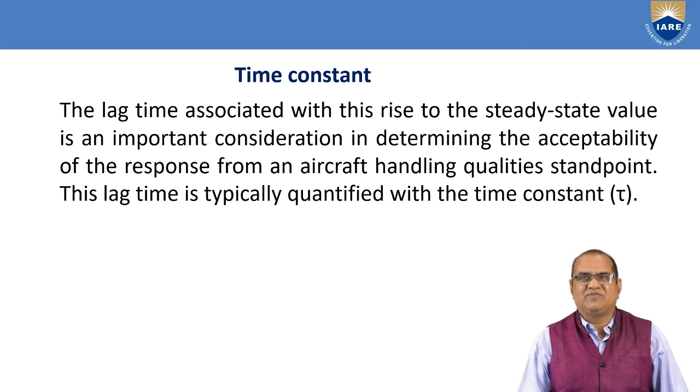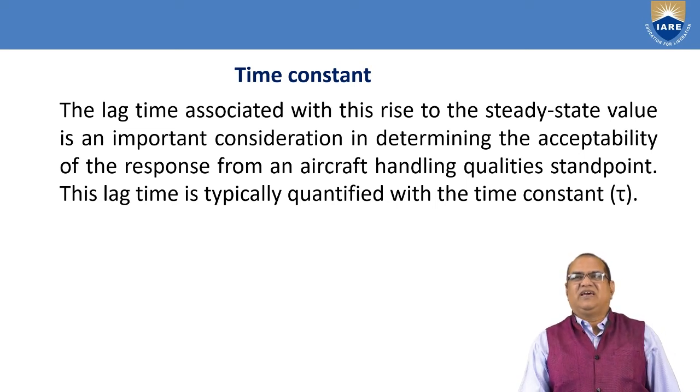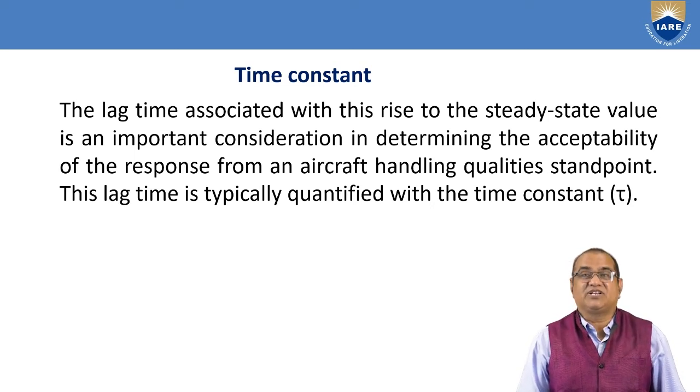This lag time is typically quantified by the time constant tau. So this time constant is a very important parameter for determining the acceptability of the response: how much time it is taking to give the response and come to its equilibrium or the required condition.